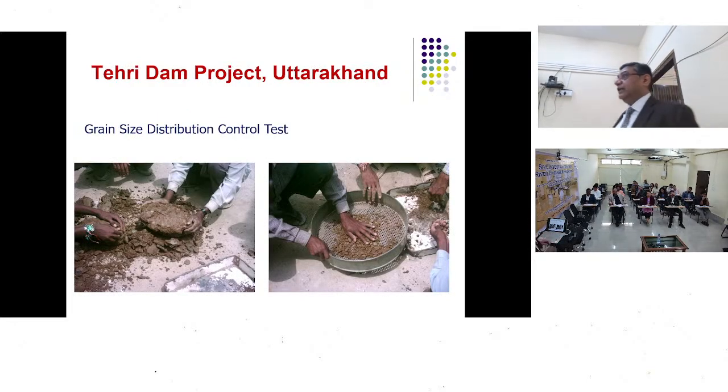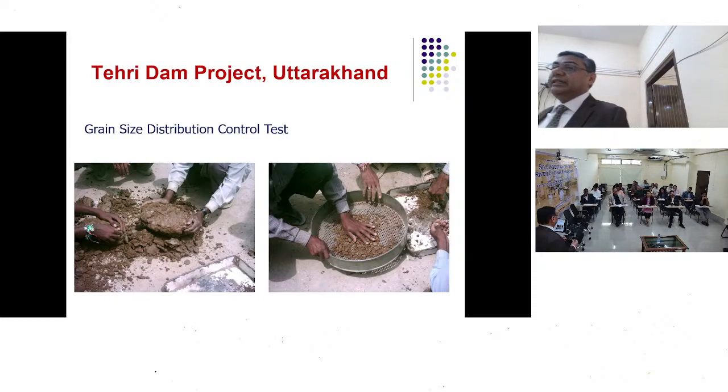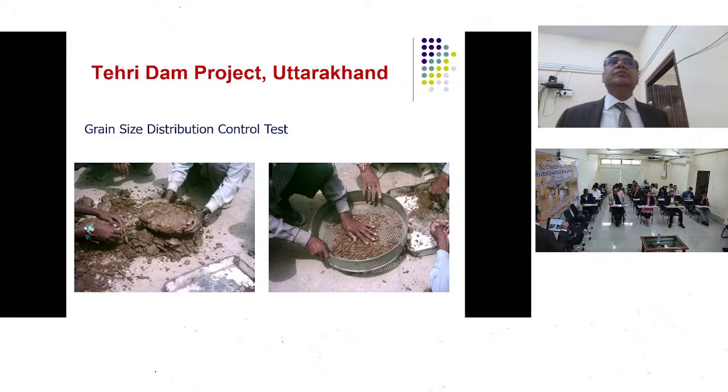Now for Tehri Dam, because as I was saying, high seismic zones were there, gravelly material was mixed into clay to form GC, gravelly clay.